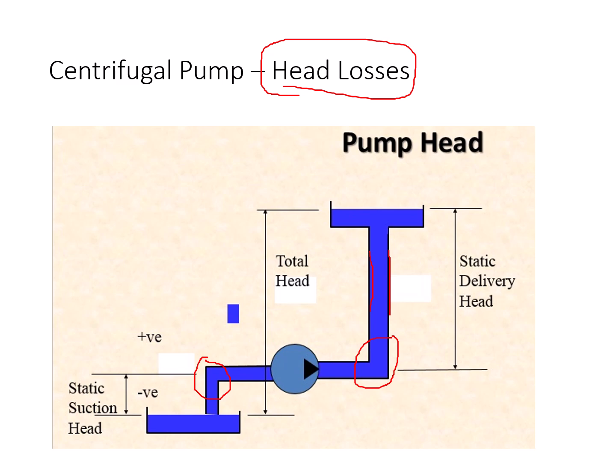Use an efficient piping layout, like shorter runs as much as possible. If you can reduce the pipe lengths, you are reducing the friction losses and the head losses.